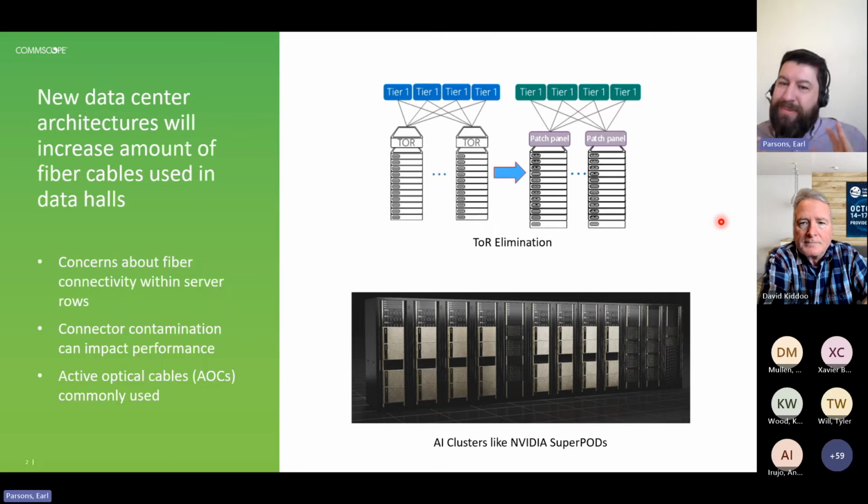Plastic fiber probably still won't have the bandwidth to go these kind of distances at these speeds. If we're going at a much lower speed, maybe, but I don't see that happening anytime soon with something other than an OM4 or an OM5 graded index fiber.